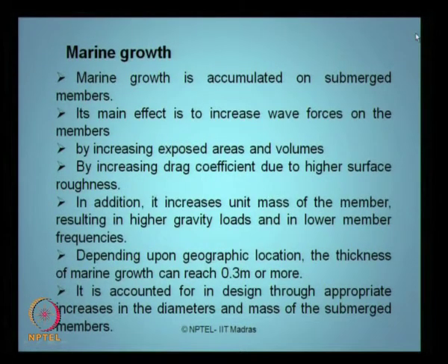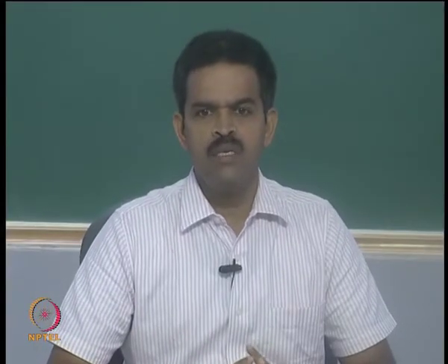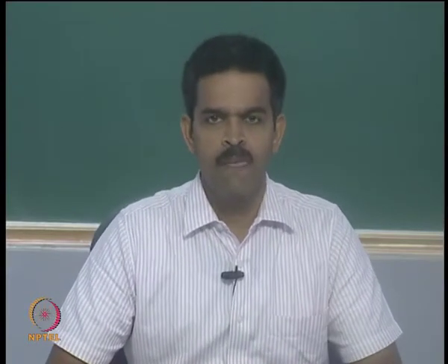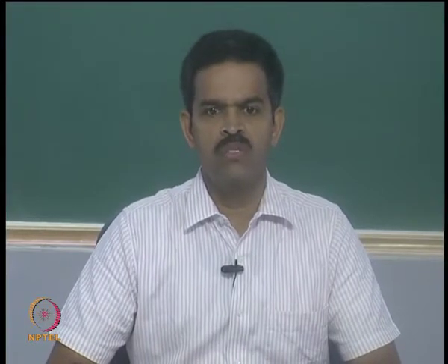The most important item, as I said, in the series of loadings acting on an offshore structure is what we call marine growth. Now, marine growth is nothing but an accumulation of marine organisms on the submerged members. The main effect of this marine growth is to increase the wave forces on the members.